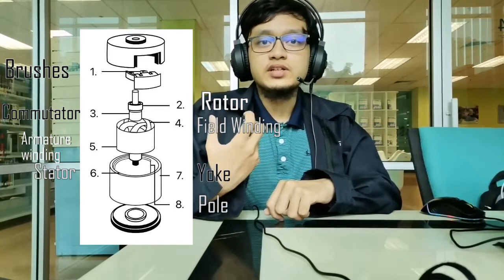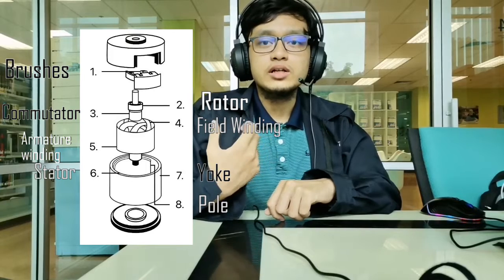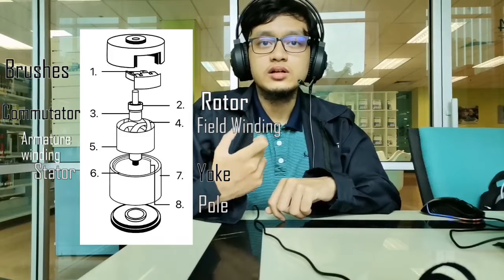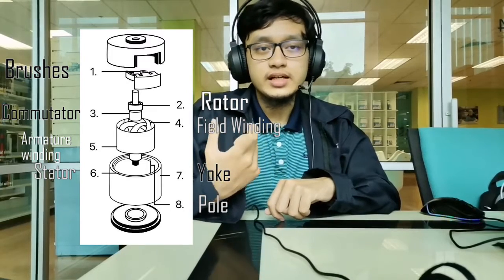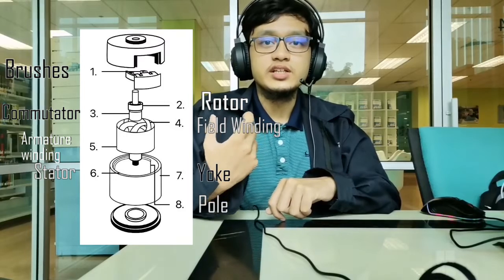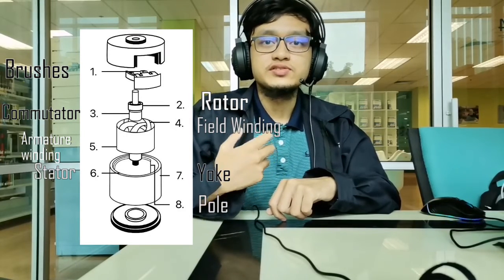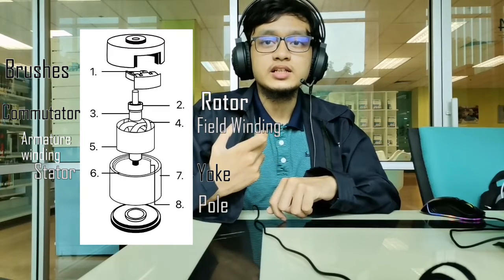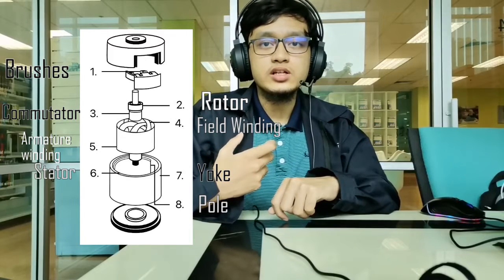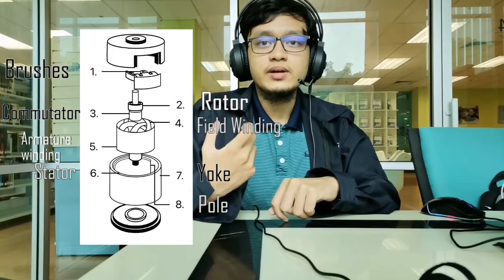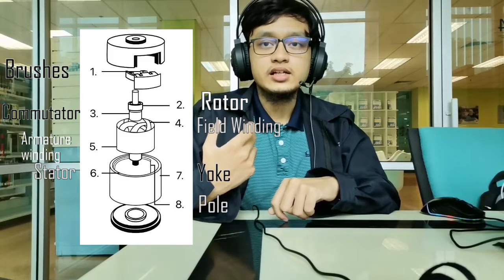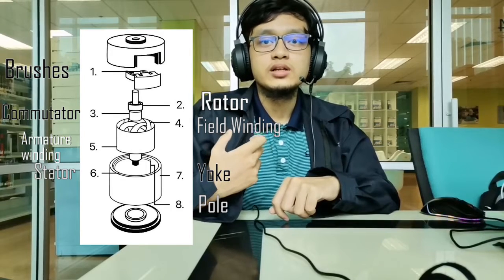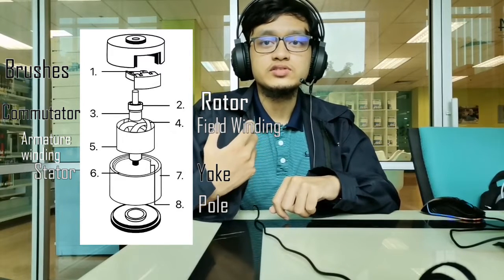Field winding is an insulated current carrying coil on a field magnet that produces the magnetic field needed to excite a generator or motor. Armature winding is the winding in which voltage is induced. And the stator is the stationary component of the electromagnetic circuit in motors. In different configurations, the stator may act as a field magnet that interacts with the rotor to create motion, or as an armature that works with moving field coils on the rotor.